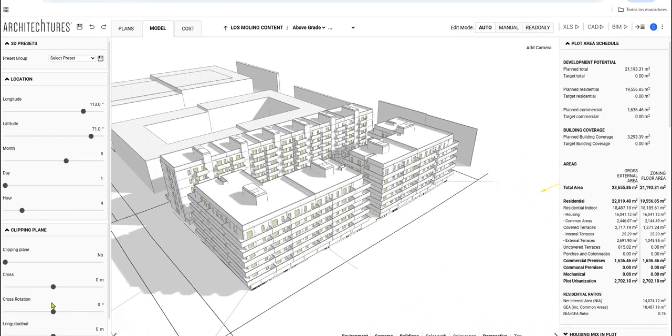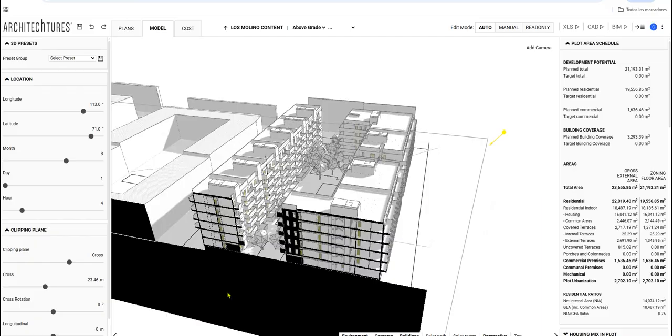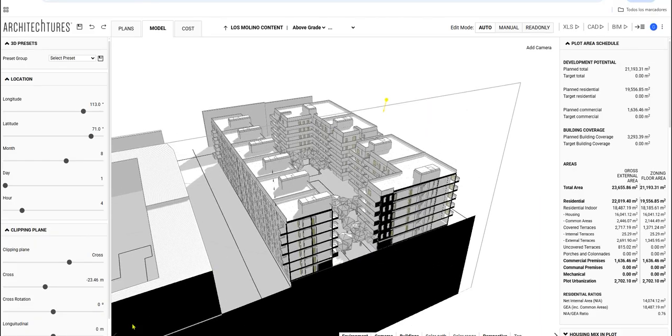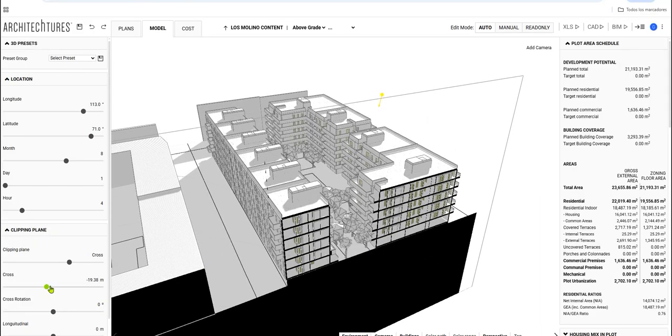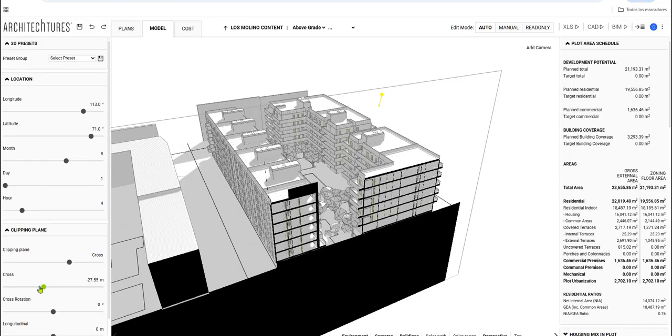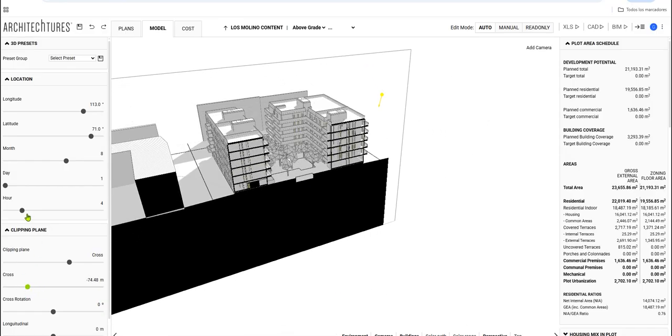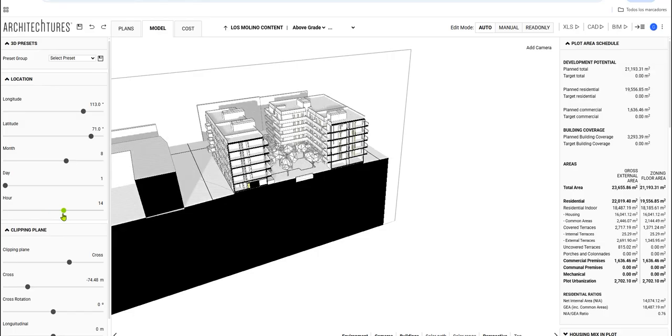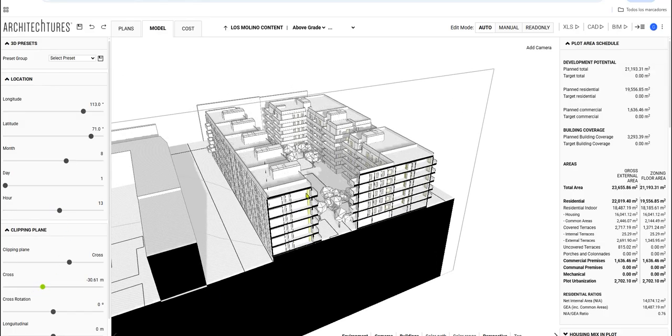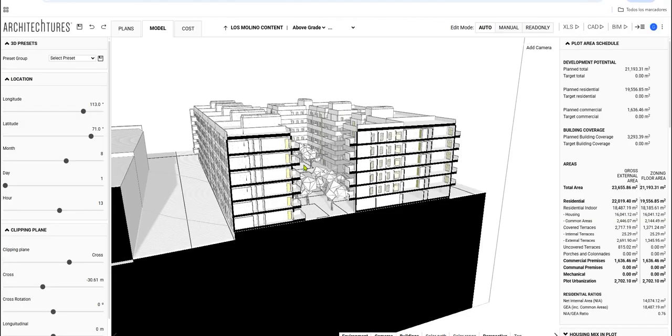Within the 3D view module, we can generate horizontal, longitudinal, or cross-sections as shown here, in order to verify and control the arrangement of all building levels and validate the implementation. As shown in this cross-sectional view, by elevating the ground floor level through the platform creation, we have minimized excavation depth below grade, thereby reducing construction costs and enabling natural cross-ventilation for the basement level, -1.